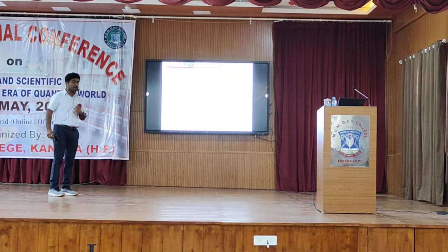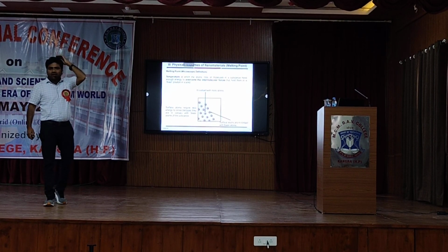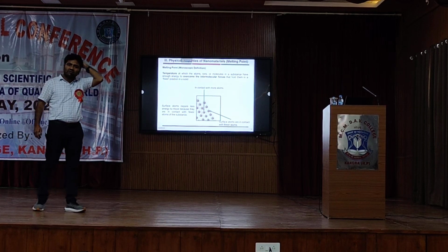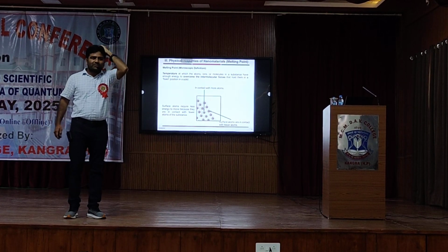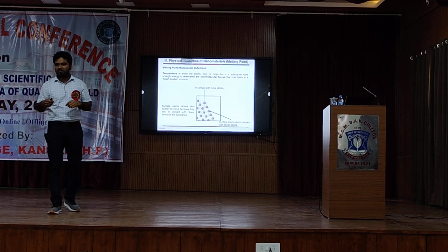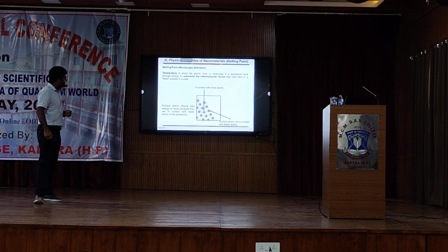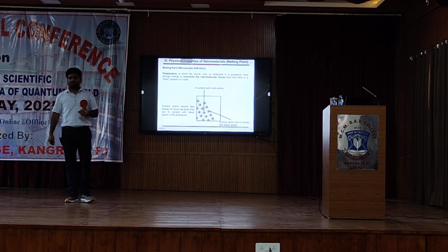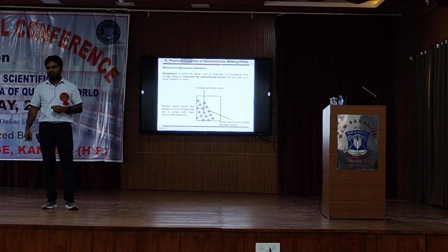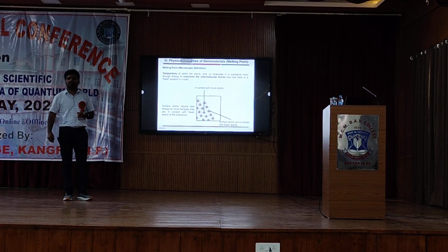And then next are the thermal properties. There is a famous Chinese idiom: gold never fears a fire. It means pure gold is not afraid of temperature, right? The ornaments are prepared at a very high temperature, 600, 700, 800 degrees Celsius; you can prepare ornaments from bulk gold. It doesn't melt, right? But if I break this bulk gold into small nanoparticles, this gold nanoparticle will melt even at room temperature. So it is not always true that gold never fears a fire. It will fear if we reduce the size of the gold nanoparticle.